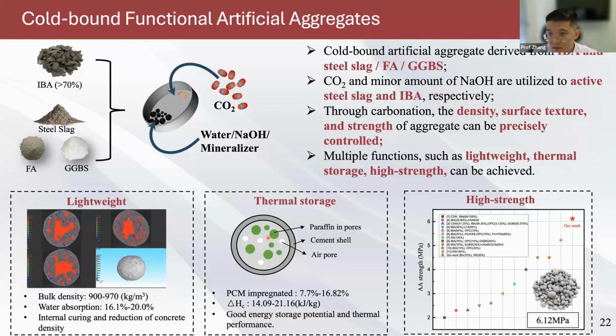And also high strength. With the help of CO2, we can achieve quite high strength compared to the literature reviews we did. We can achieve the highest strength, which matters because low strength is normally one of the primary drawbacks of artificial aggregates.